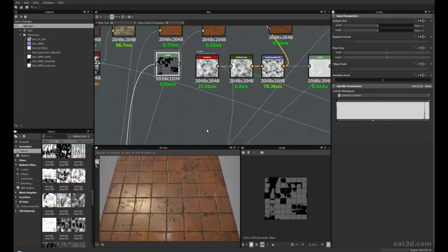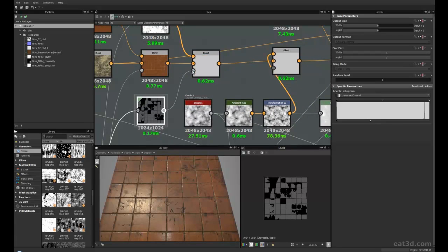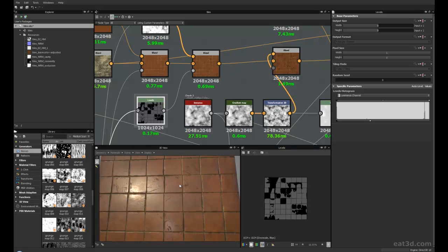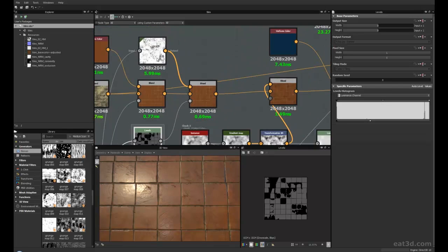As we know, white is seen as opaque, and black is transparent, and then you get the degrees between the white and the black. So when I'm pulling this down, as you can see, it's making it darker, and in effect when I plug this into here now, you'll see they've gone. This is how we can control how much of the dirt we want coming through.